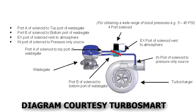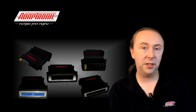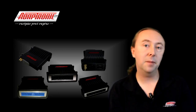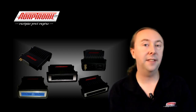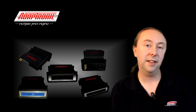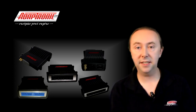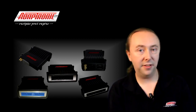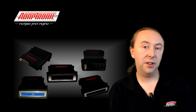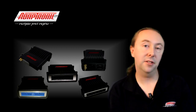So what this means is that there's a much wider range of pressure differentials that you can apply to the wastegate itself, and this makes it a lot easier to overcome higher exhaust back pressure, pushing the wastegate open. So this allows you to get a much higher range of boost levels with the same spring in the gate. You can also buy these 4-port valves, which conceptually are the same as two 3-port valves in the one package to make it a lot simpler to install. And electrically, if you're going to run the two 3-port valves, you just connect them in parallel off the same output from the ECU. Now, the limiting factor on a 4-port valve configuration is when the exhaust back pressure plus the spring pressure of whatever you've got in the actuator becomes more than the boost pressure that you're trying to achieve.